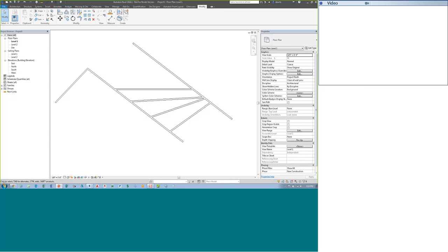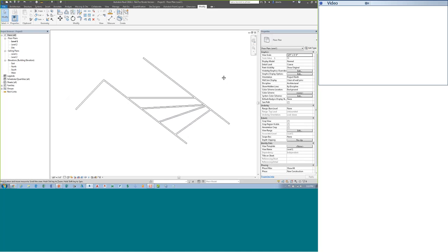I'm also being cognizant of time. Command number 11, save command. We've got to save our work, right? So we hit the save command, boom, you're done. You have an icon next to it called synchronize and modify settings. This is save to central.